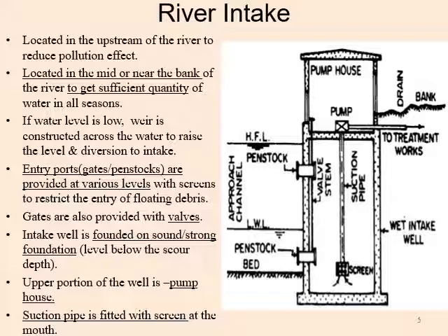This portion is named the well. It is shown here as well, the wet intake well. Wet means the water is present here after opening of the gates, so it is named the intake well. Screens are also provided. Screens can be provided at the entry points or entry gates, but here the screen is provided with a suction pump pipe which is connected to the pump for pumping the water. Gates are also provided with valves. The valve is shown here.